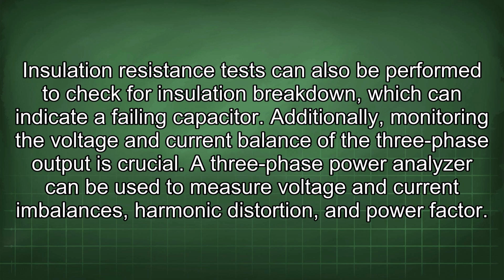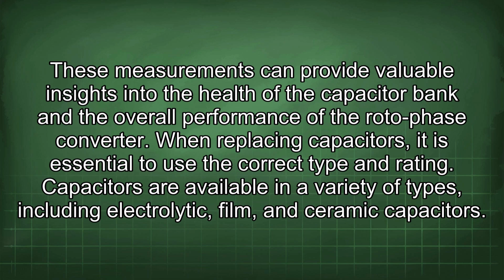Additionally, monitoring the voltage and current balance of the three-phase output is crucial. A three-phase power analyzer can be used to measure voltage and current imbalances, harmonic distortion, and power factor. These measurements can provide valuable insights into the health of the capacitor bank and the overall performance of the rotary phase converter.